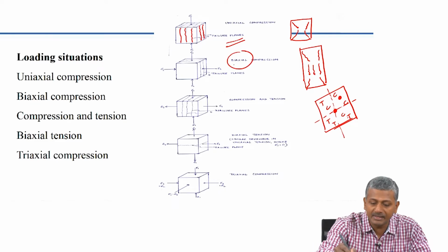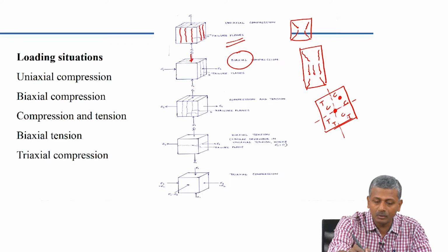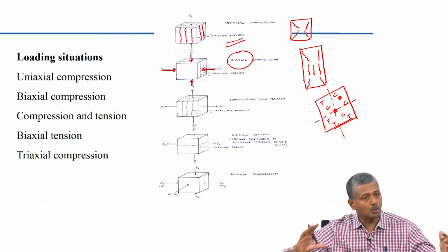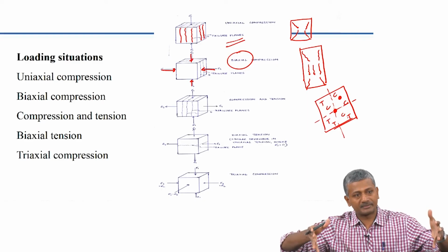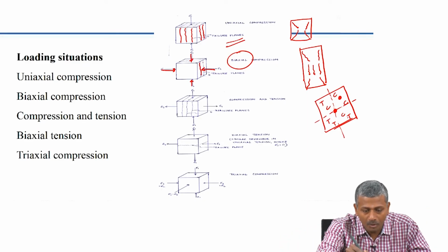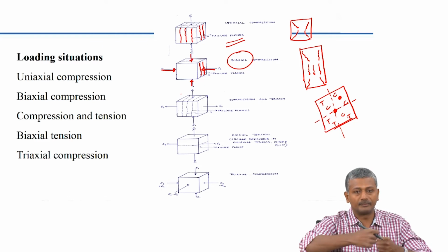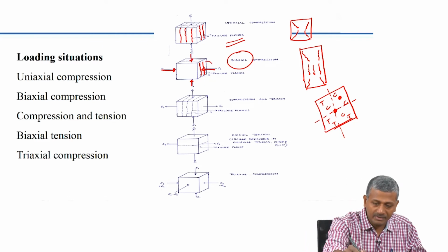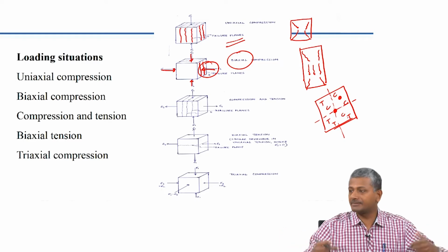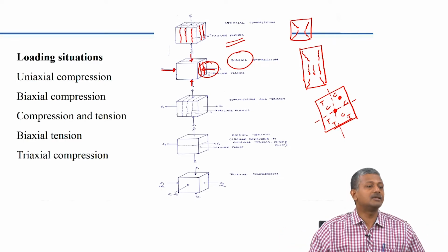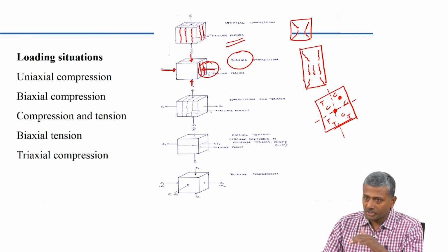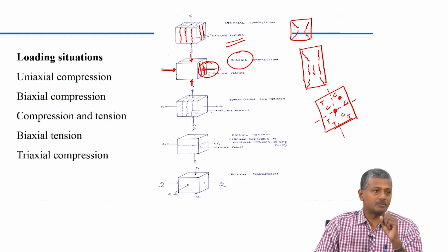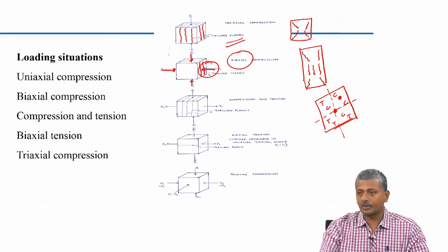Now, when you look at biaxial compression, loading is along two sides of this cube, indicating that along one side there will be some restraint offered to the opening of your specimen. In other words, the cracks now will form only in the third direction, which is free to move. Because of this additional restraint caused by the biaxial compression, you actually get a strengthening of your material. In a biaxial compression state, the actual strength that you measure will be higher than the uniaxial strength by a certain amount, and I will talk about that in just a minute by looking at the biaxial stress interaction curves.